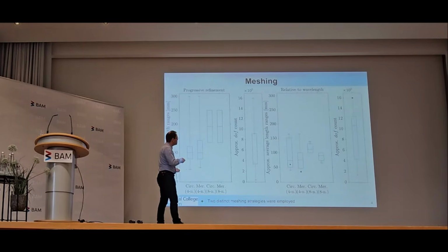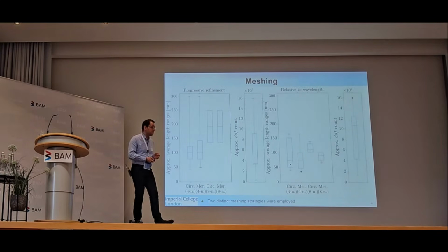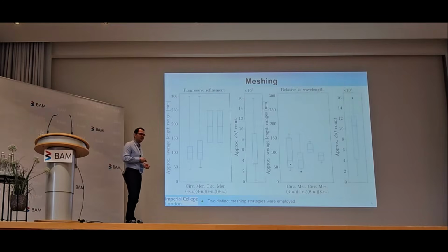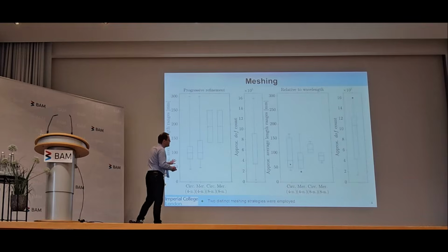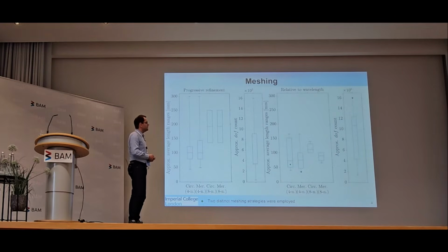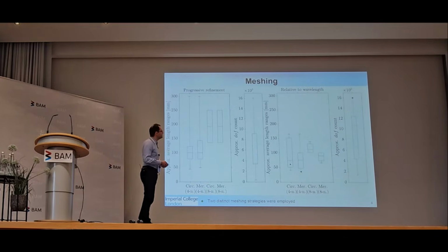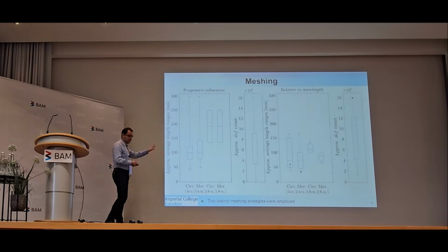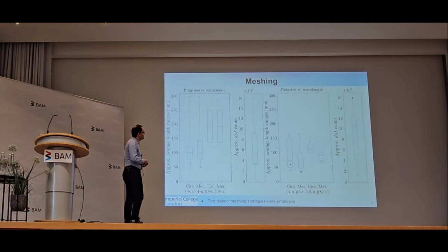And I think many of these metrics were done on the basis of an LA, which is a linear elastic stress analysis, so not even a buckling analysis. It is not sensitive enough to the feature that matters. So that was the first interesting finding, just some meshing assumptions. And since a mesh very much influences the results that you get, if this is incorrect, then everything else will be incorrect. So that was the first set of interesting results.